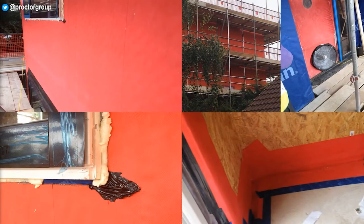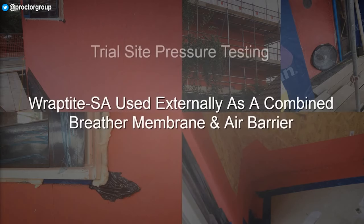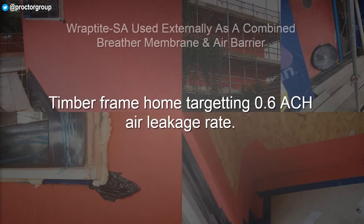Case study, Kingspan Potton. The benefits of an external airtight layer were proven on a site trial conducted by Kingspan Potton. They utilised the Raptite self-adhered vapour permeable membrane as an external air barrier. The Raptite product itself is highly vapour permeable, yet airtight, acting as an air barrier, and it's self-adhered to ensure a continuous layer can be achieved easily on site. The project was a timber frame house which was targeting an air leakage rate of 0.6 air changes per hour, which is essentially a passive house.